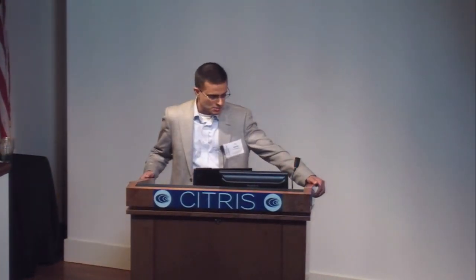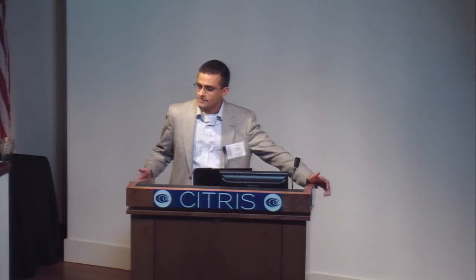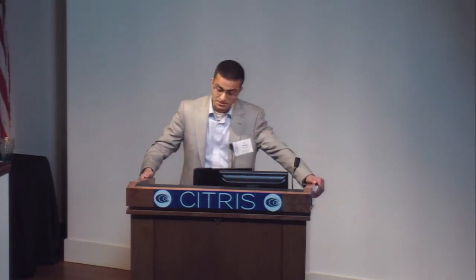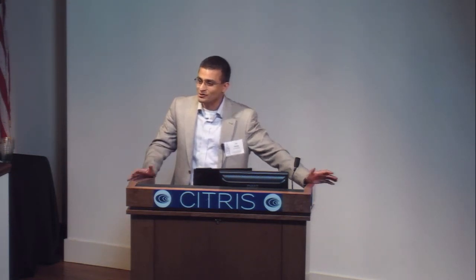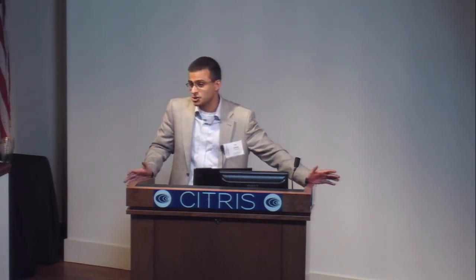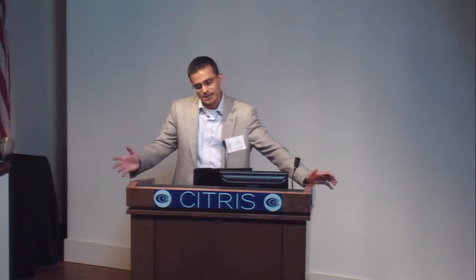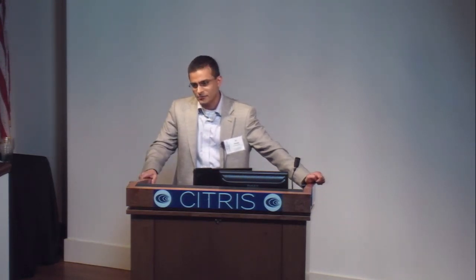In fact, we did this for indium arsenide as well, and we presented that as the big advantage of surface charge transfer doping rather than body, substitutional doping. Whether that will help in terms of band edge roughness, we don't know because we don't have the results, but we think it should because it's not creating those local defect sites. But that's something we have to look at down the road.